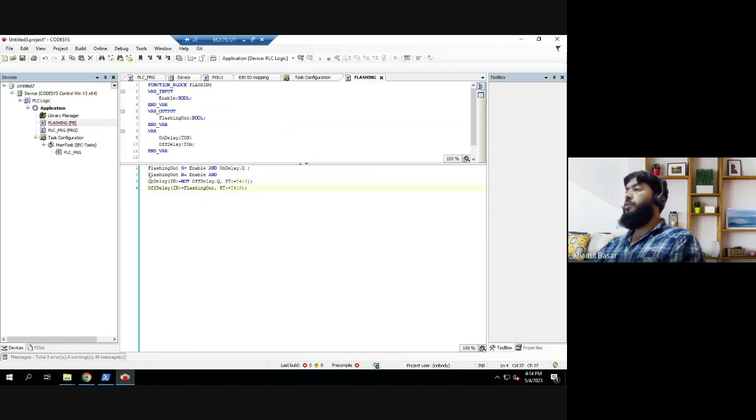One second running. We set this one. So once we set this, we start this timer. After this timer, we get this done bit. So we will get a done bit of this one, and then we reset this. Once we reset it, this timer resets also, and when it is set, this timer also resets. So this thing continues in a cycle.